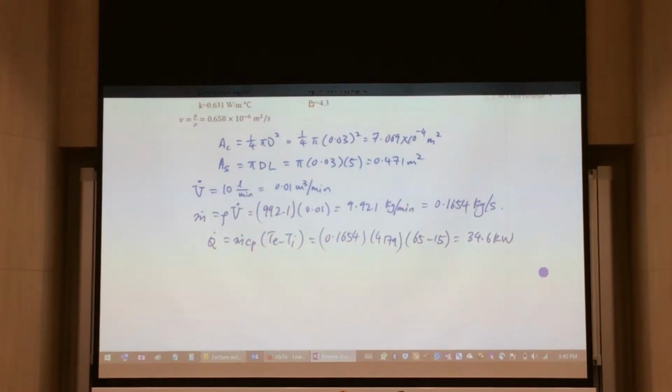So this is a power rating of the heater, because the heater needs to supply this amount of energy or power in order to heat up the water that's flowing within it. So we could make use of that in the following equation. I want to find out what is my Q dot. And actually Q dot is equal to Q, it's a new symbol, divided by A. So this Q dot is equal to H multiplied by Ts minus Tm.